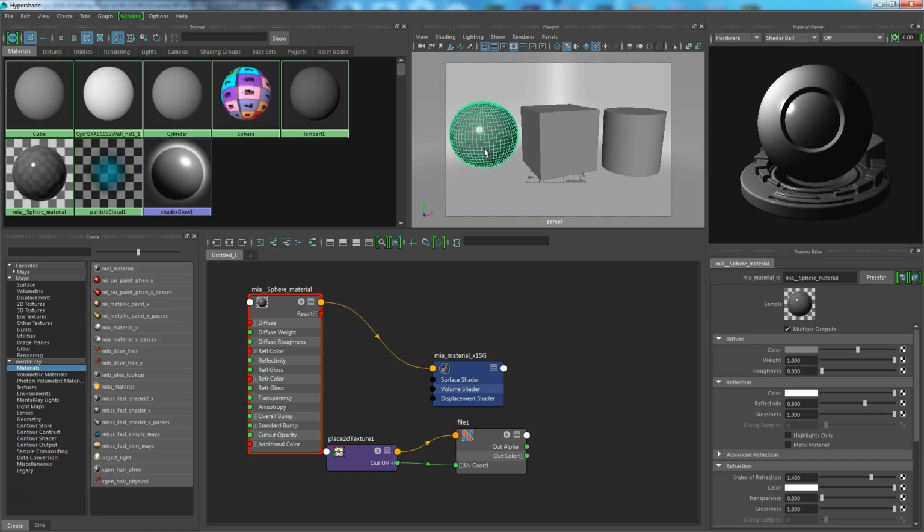Okay. So now, the reason we're not seeing the texture on here is this sphere has no mapping coordinates. Now I kind of did an evil thing, and I set you guys up, because this is the nature of the project. By default, spheres have mapping coordinates on them, and all of these primitives have mapping coordinates, but I removed them so that you would have to come back in and learn how to put your mapping coordinates on those. Okay.